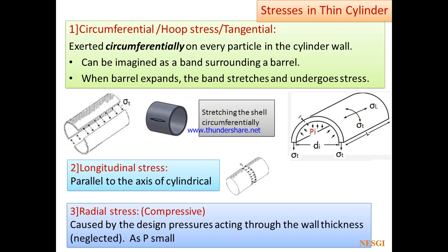So let us see the thin cylinder, the theory related to the thin cylinder and problems on the thin cylinder. Here you can see stresses in a thin cylinder. Basically, in cylinders, three types of stresses are induced because of the fluid inside the cylinder. Here this is Pi, the inside pressure. Because of this, a stress is induced in the cylinder.